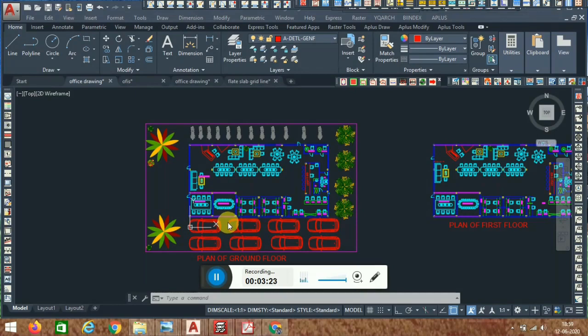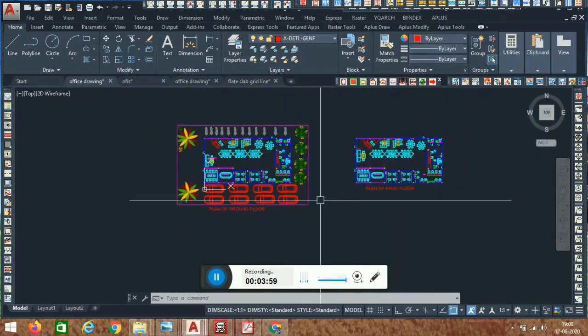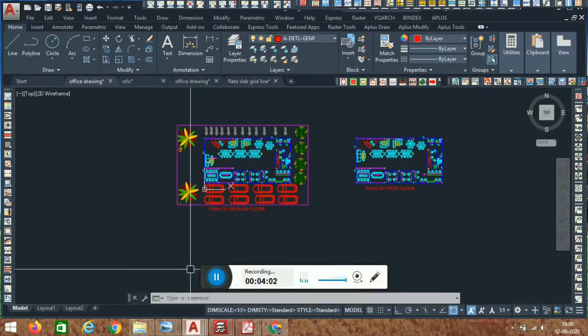At first we are talking about the thickness. We have to consider the minimum thickness for the flat slab, which is 120 mm, and for the conventional slab some codes say 80 mm and 100 mm. The live load should not be greater than 3 times the design dead load for the flat slab, but we don't have such a rule for a conventional slab. These are the considerations we have to study, and then only are we able to design and analyze the flat slab. So let's go to the software, and we will explain more through the software.